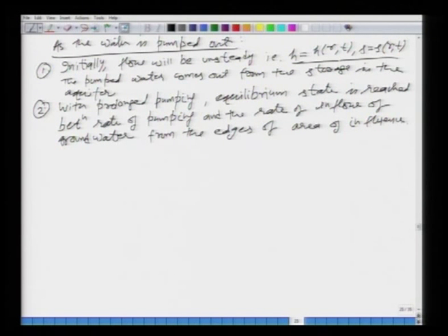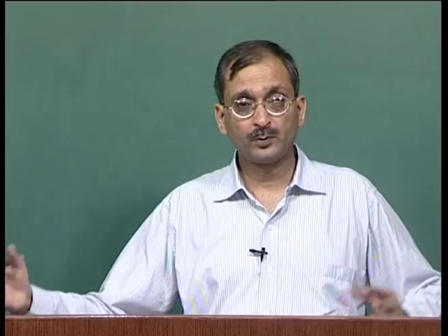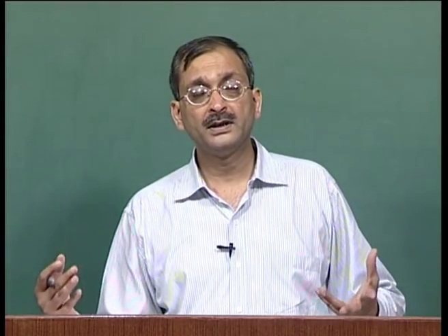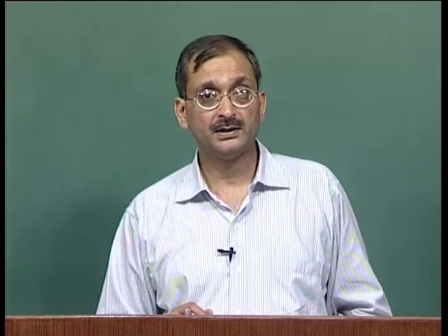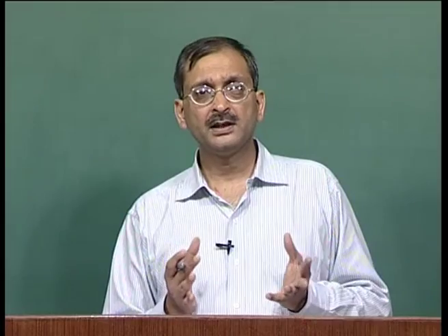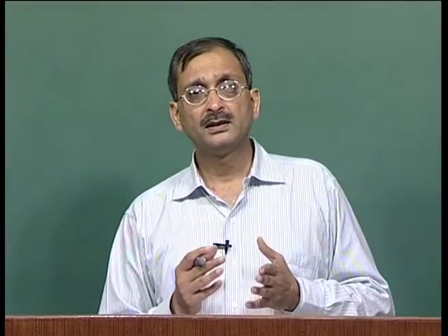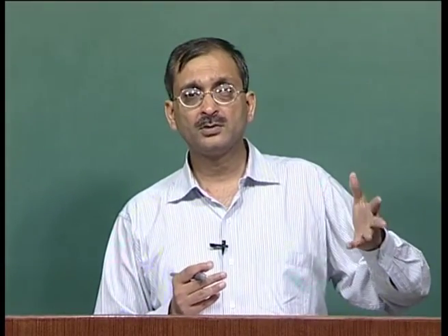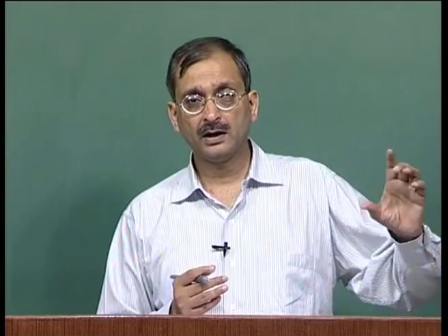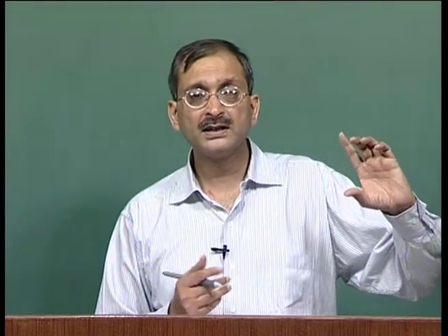So, what we are saying is that if we continue the prolonged pumping, an equilibrium state will be reached, or things will become steady state. What do we mean by saying that the flow will be steady state? If you make an observation in the observation well, the drawdown will be constant as a function of time.